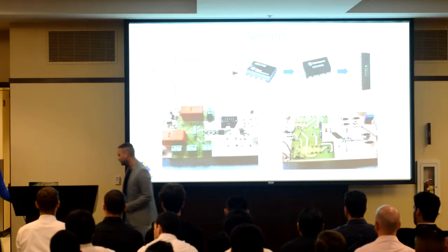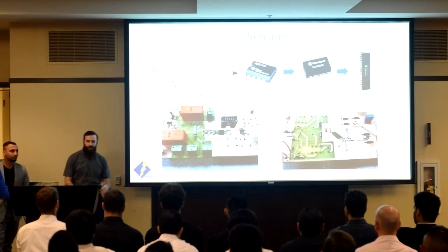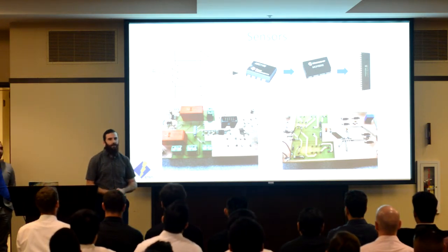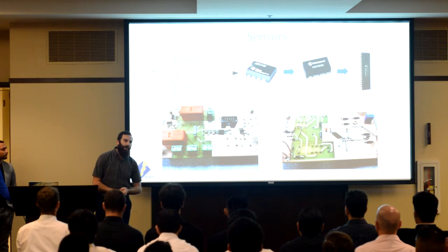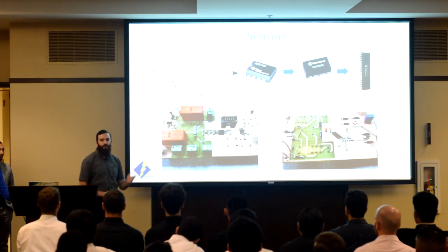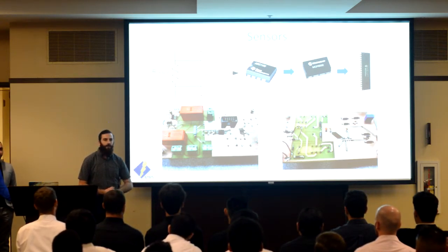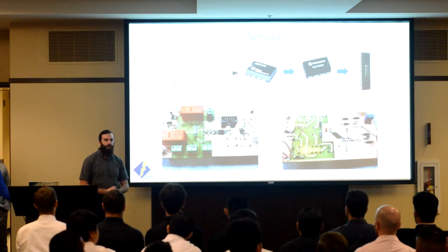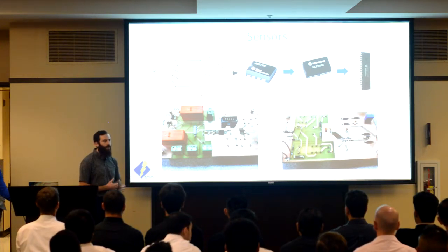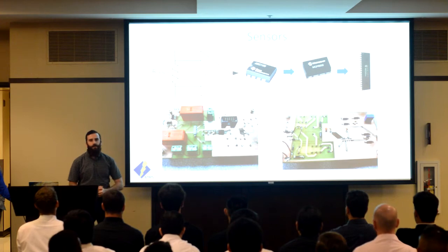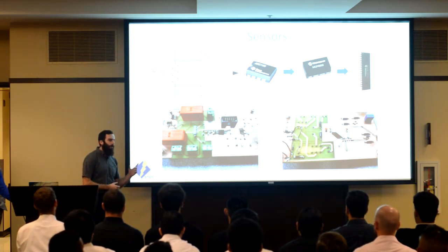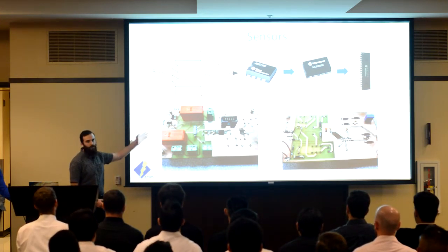Thank you, Bashar. My name is Jeffrey, and I designed these sensors. So in order to get those nice looking waveforms you all saw in the GUI, what we need to do is sample the currents and voltages in our AC system. So in order to do that, we use some very simple shunt and series resistor topologies. In the example here, you can see a shunt resistor that is going to create a small differential voltage across it as the current flows through it.